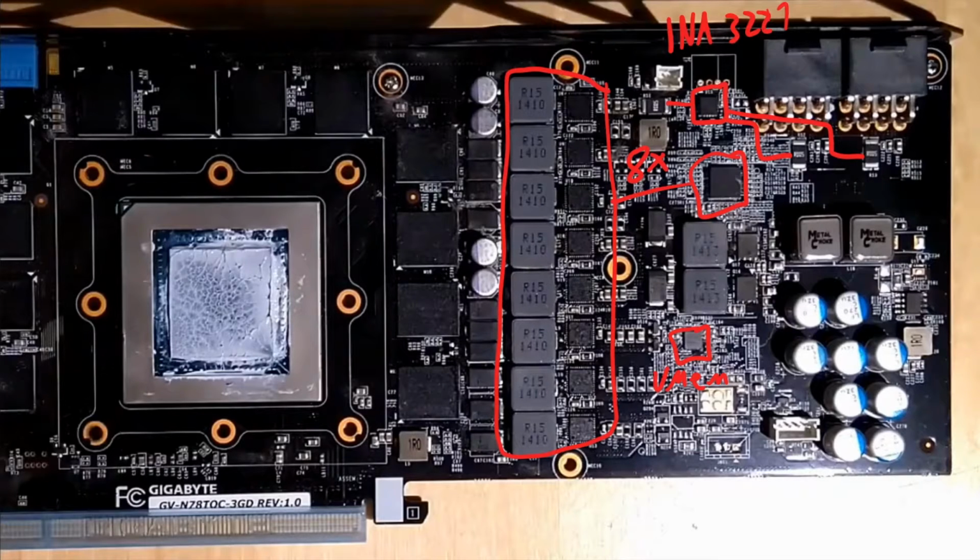I don't have a picture of that right here right now, but if you watch that video, you will see that those 2 inductors here are missing. The reference board does only have 6 inductors for 8 power stages, so it is still an 8 phase. It's just that the 8 power stages are sharing 6 inductors, and that's just a thing you can do.